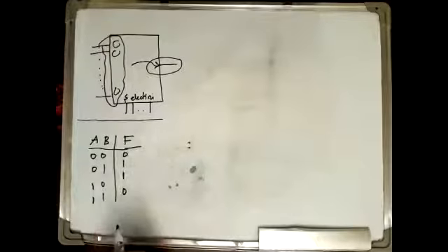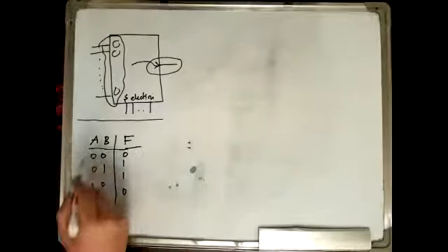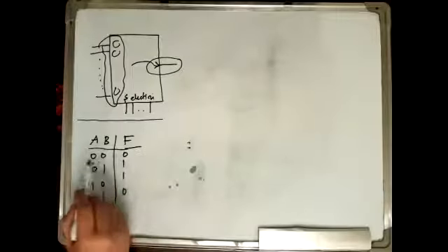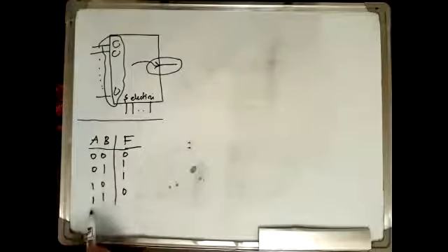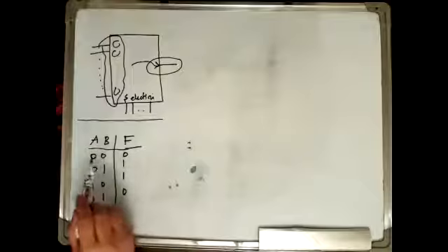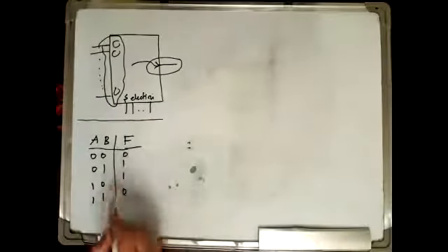What is the size of the MUX needed to implement this function? 4-to-1. How many choices do we have for the function? We said 4. So we need a device through which we can select one of these possibilities to appear for the function.